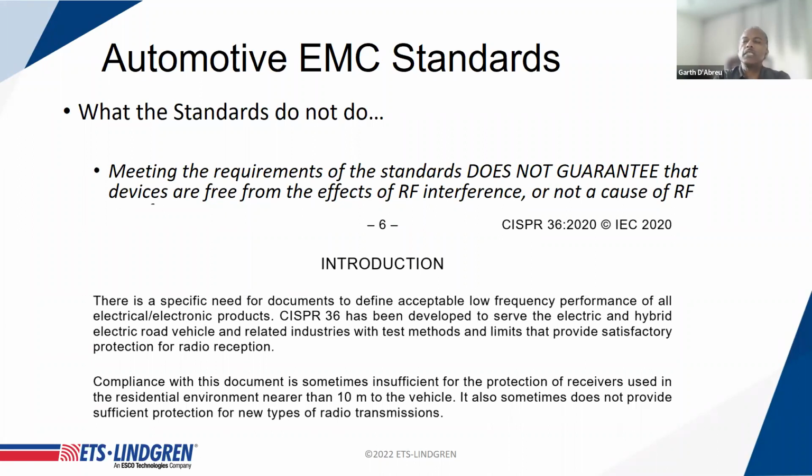When it comes to a lot of these EMC standards, the intent is to provide a level of resilience to the RF environment, the electromagnetic environment, but there are no guarantees. If a product is tested to a standard and meets the requirement of the standard, it does not guarantee that that product will not create interference, and it will not guarantee that that product is free from being interfered with by other RF sources in that environment. So that's a very important point to make about what standards can and can't do.